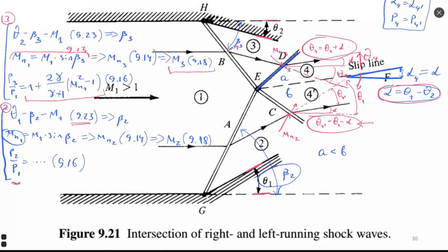So when we decrease alpha, we increase the angle between the slip line and the shock wave, and this results in a bigger value of the pressure ratio. Opposite, when B is bigger, it means that the shock wave in the lower part is stronger. We can decrease it by also changing alpha, and then step by step, even by algorithm, by calculation, the program can choose the step of change of alpha from one iteration to another. We can find alpha in 3, 4, maximum 5 iterations, that corresponds to equilibrium between A and B.